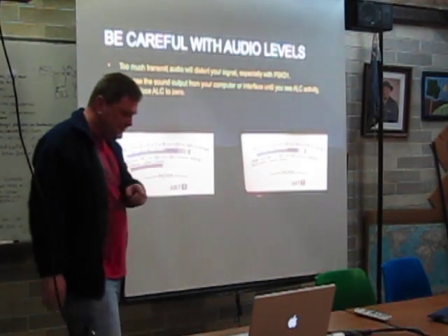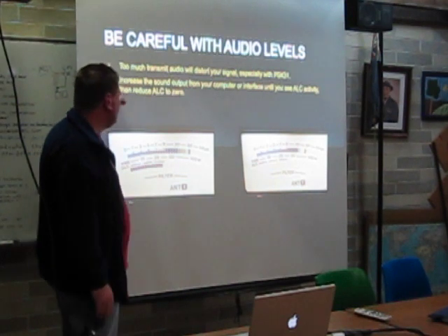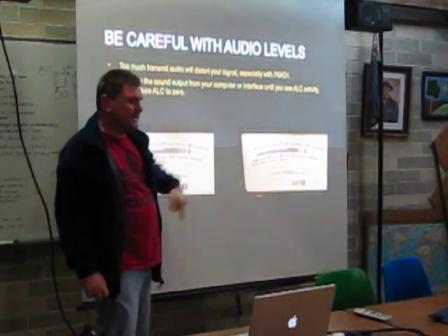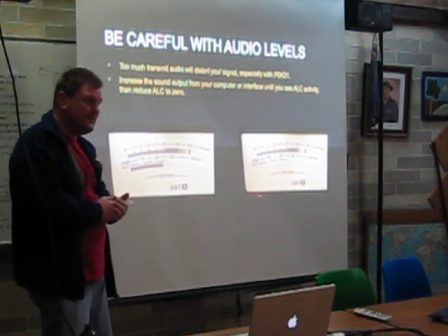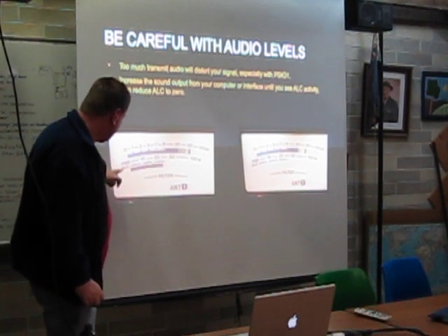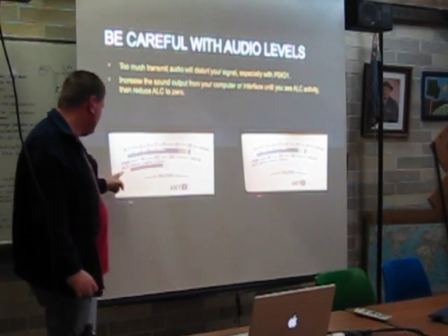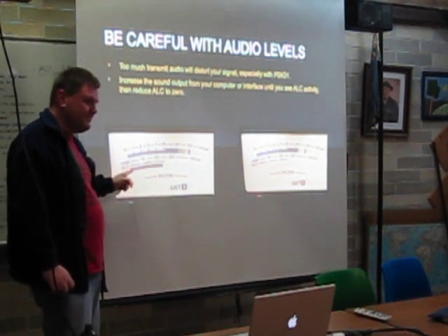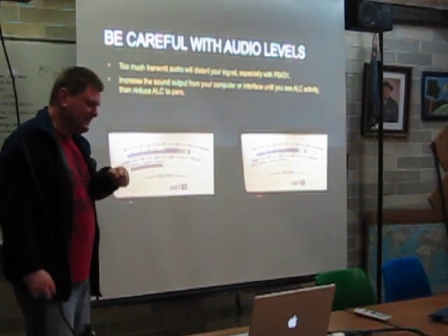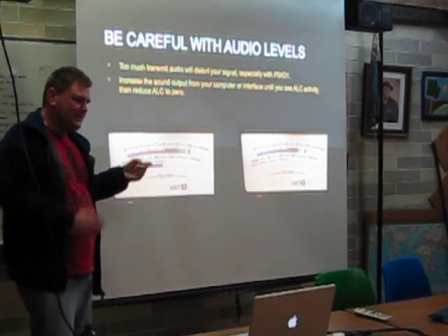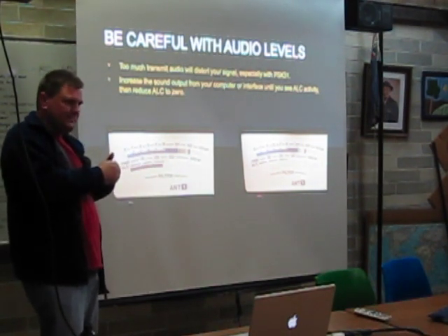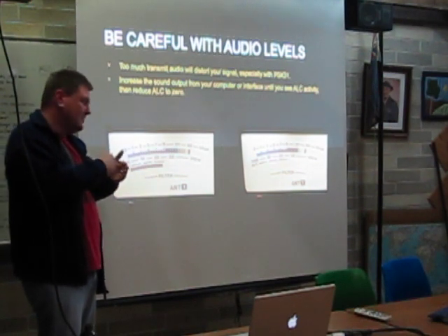So there are some other modes as well. The important thing with these signals though is you need to get the levels right. Otherwise you can get distortion, and that's particularly important with PSK. As I mentioned before, linearity is very important with phase shift keying. So here you can see you've got the ALC, automatic limiting control, in the transmitter. When you see some activation there, what it means is that there's a feedback loop inside the radio that's reducing the gain of the transmitter because otherwise the signal's too strong.